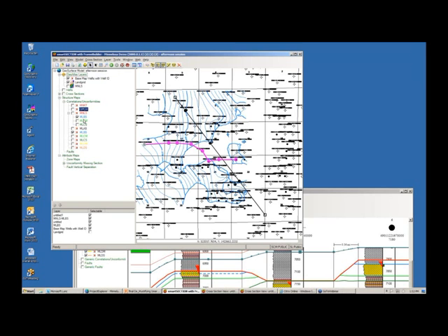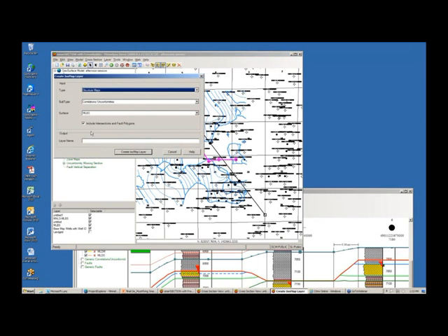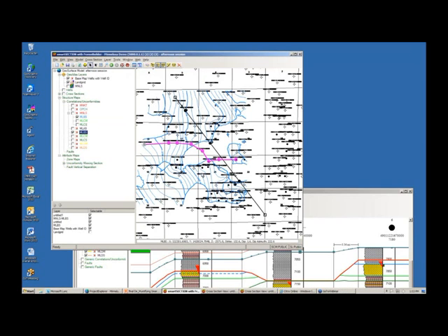Another thing you can do is instantly take this map and select the surface that you've made and create an isomap layer and take it back to Geo Atlas, give it a name. You can include intersections and fault polygons. Take it back to Geo Atlas and actually use a different mapping algorithm and work with this layer. Right now in Frame Builder, the only layers that are created use a triangulation method of creating the contours.